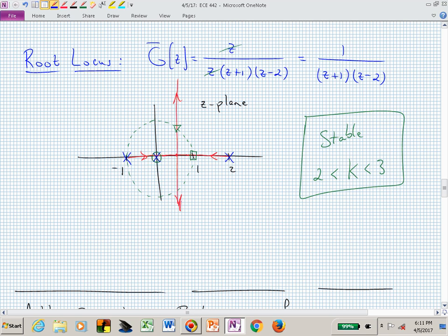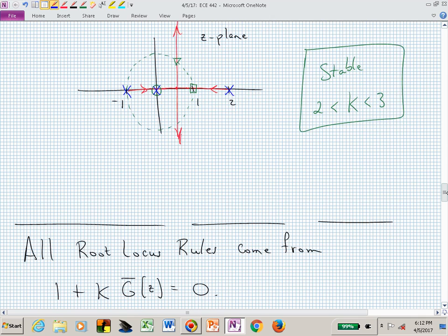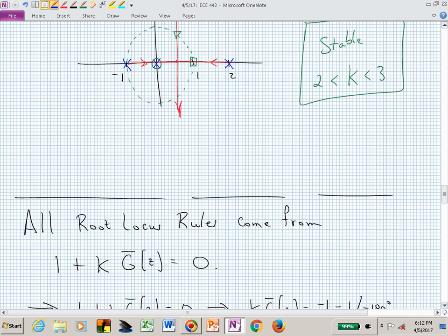So in reality, you probably want to be somewhat inside the unit circle for your dominant poles or all of your poles. If you locate something on the unit circle, no, you probably don't want that to happen. You shouldn't put anything closed loop on the unit circle.